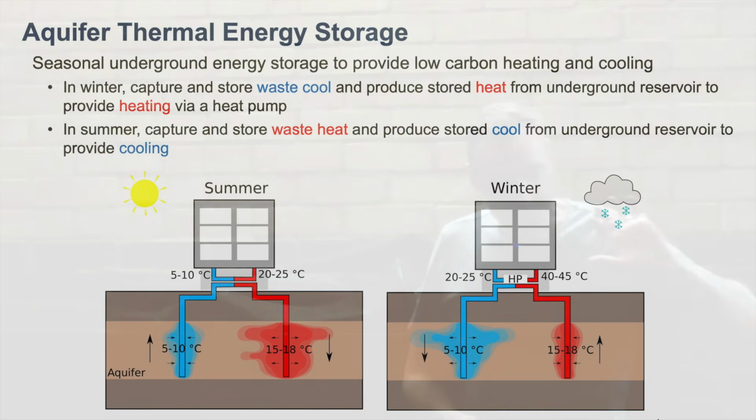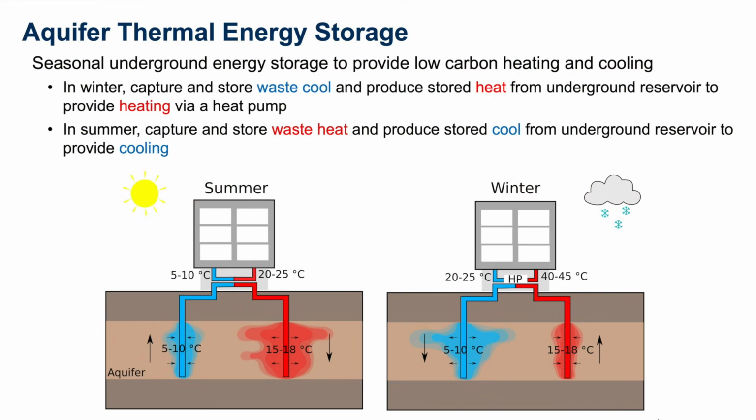So what we do in aquifer thermal energy storage, as I said, is that in winter we're producing groundwater, passing it through our heat exchanger, and using a heat pump to boost the temperature, and then we re-inject the waste cool water back into the aquifer.